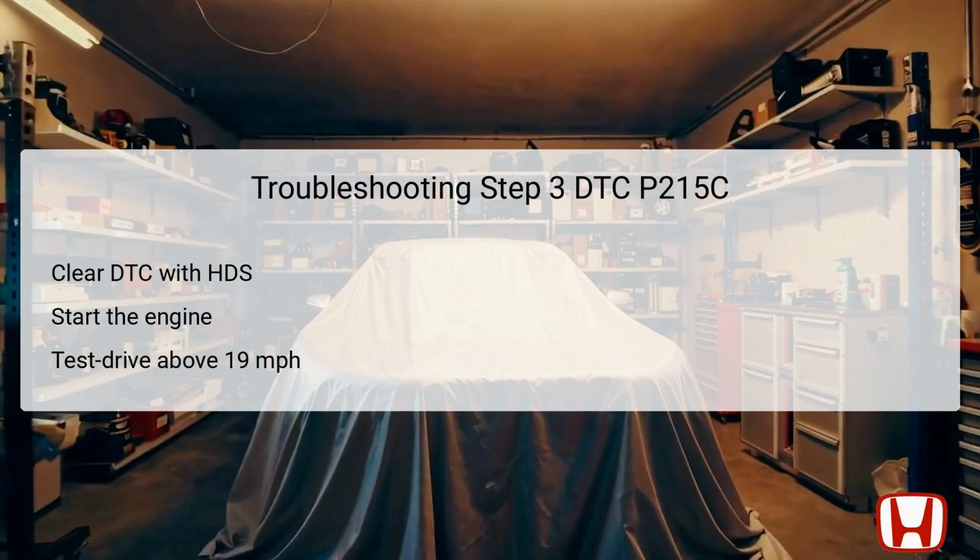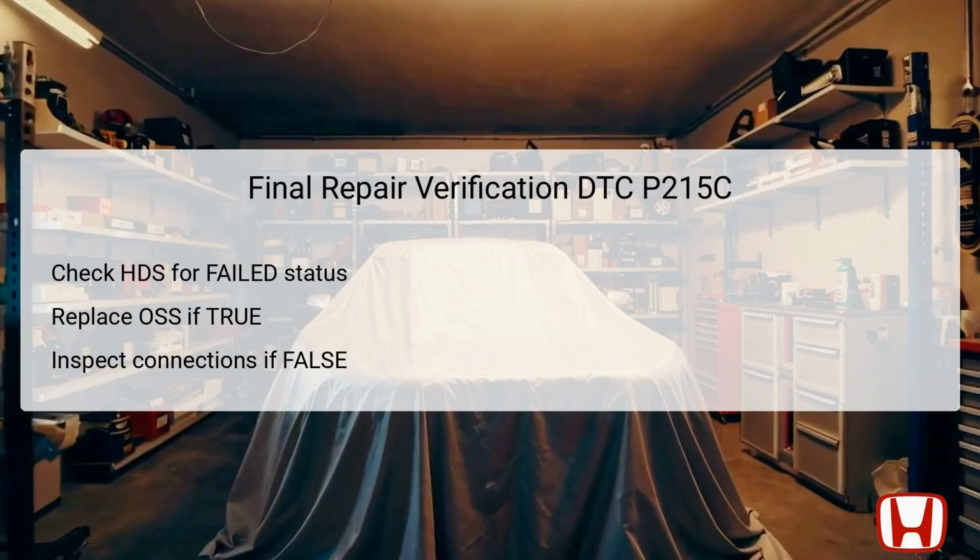The final step in repairing DTC P215C revolves around the results from the HDS after the test drive. If the HDS indicates a failed status for DTC P215C, it confirms that the problem persists in the system, necessitating the immediate replacement of the output shaft speed sensor. Conversely, if the HDS signifies passed, the current system operation is satisfactory, albeit intermittent issues may persist.